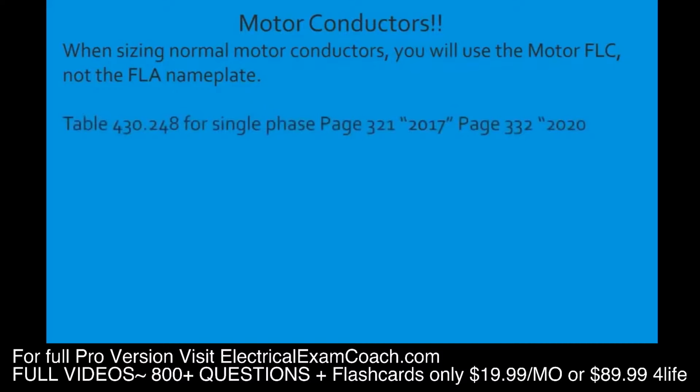We're going to find these values in table 430.248, and that's for single phase. It's on page 321 of the 2017 or page 332 of the 2020. I want you to head there now, pause the video if you need to, and we're getting ready to go over this table. I'll give you a little hint. If you are able to tab your code book, there is a motor FLC tab that will take you right there.